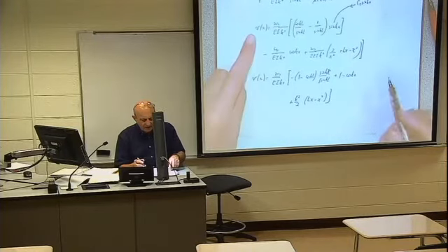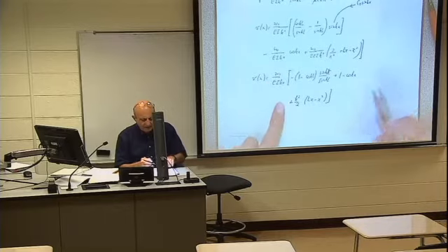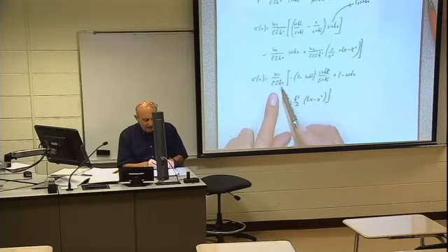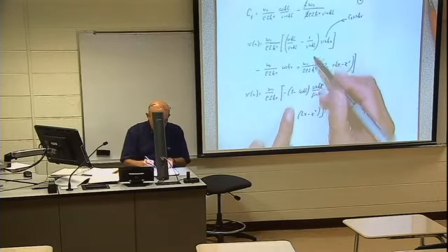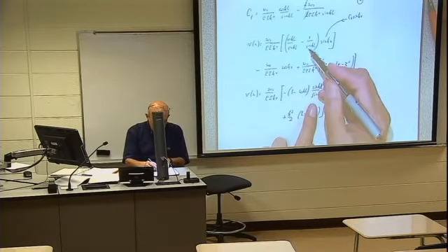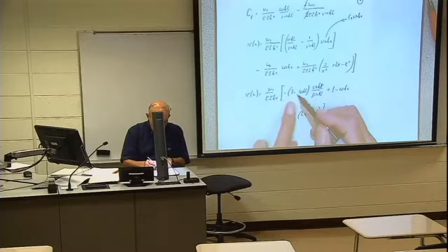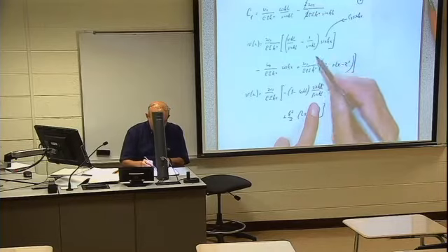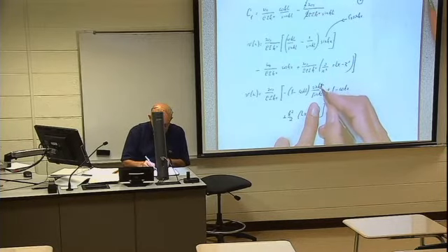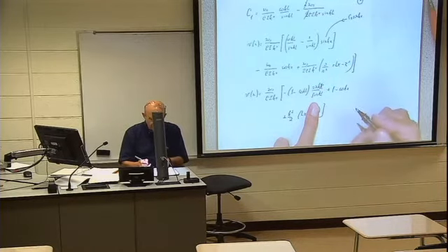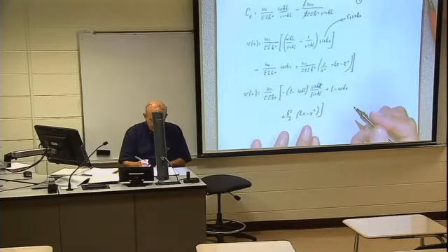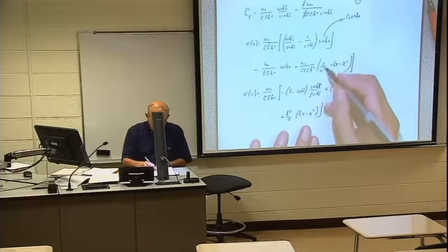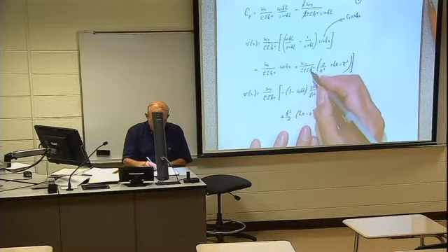So then I can rewrite in a more compact form. W0 over EI k to the fourth power. Then look, sine KL can be taken out, minus can be taken out. It will be 1 minus cosine KL, sine KX over sine KL. Then these 2 and 2 are canceling each other. I will get k to the fourth power.